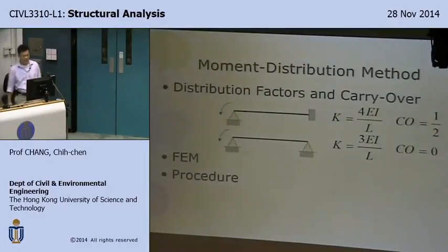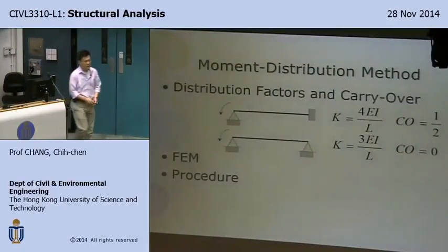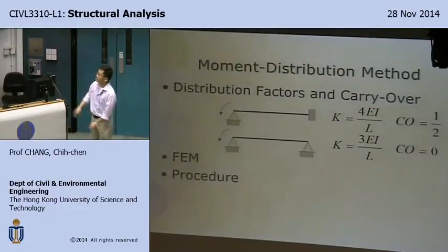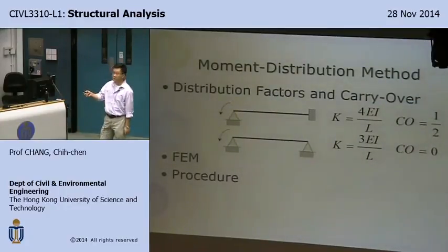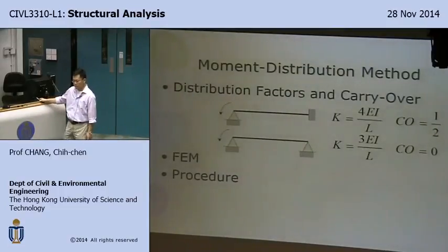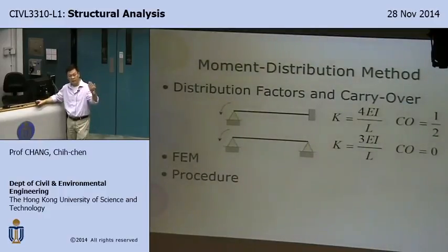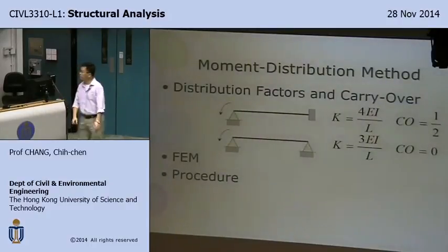And the last chapter we cover is the moment distribution method. And I started that method using two very simple conditions and illustrated to you that it boils down to the calculations of distribution factors. All right, so the procedure is fixed end moment, balance, distribute, carryover, etc., etc.